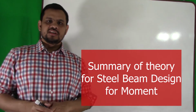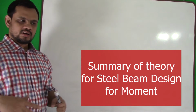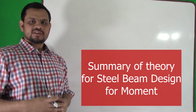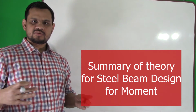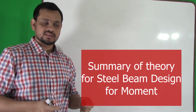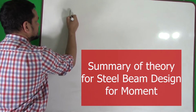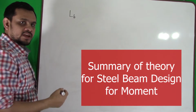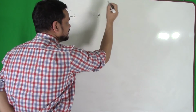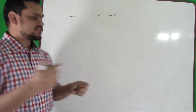Okay, we will see steel beam design again with some example. So we learned that the capacity of a steel beam depends on the unbraced or laterally unsupported length. Again, a laterally unsupported length is represented by LB, and we also learned about LP and LR. What is LB? LB is the laterally unsupported length.